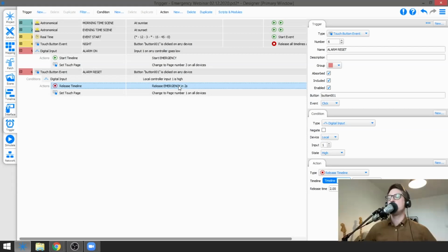I also noted another question comes in, and I think I'm going to take the liberty to answer that, because it's saying we are controlling emergency fixtures, and that is not what we're doing here. What we are talking about here is using the Pharos controller to be supportive to an available emergency system. By nature, just the way DMX works, or ACN for that matter, those are not systems that you should use for the official security systems.